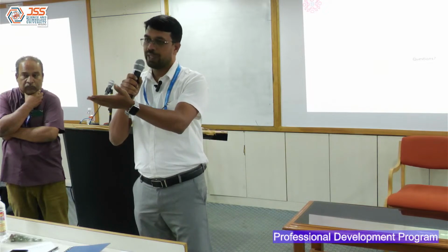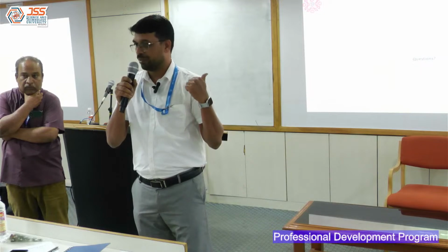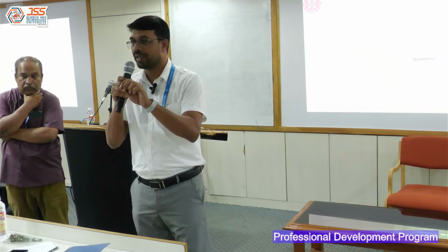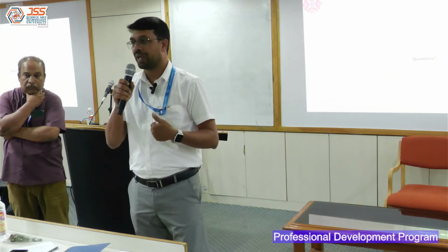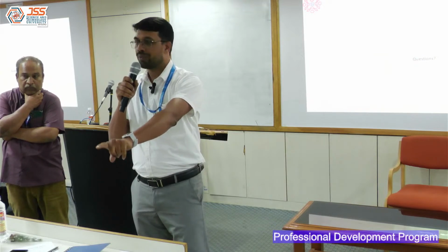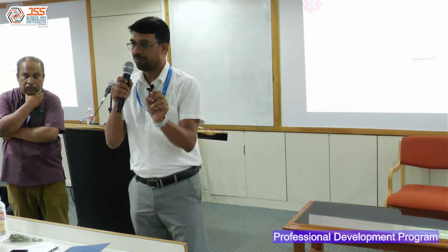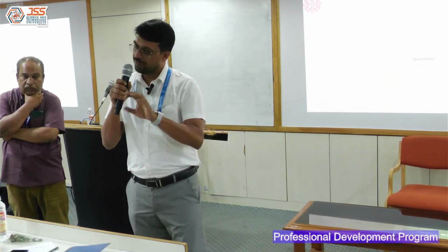Typically when you are talking about a medical application, accuracy matters a lot. So my test coverage matters a lot. Again, I should know what are the conditions in which this particular end product can be used. Based on that, I have to refine my testing. And as I told you, some of the requirements would be coming from the physical design, where they have the sign-off corners. It has to work at such a low voltage, or they would say minimum voltage, maximum voltage, temperature, pressure, everything comes into the picture.